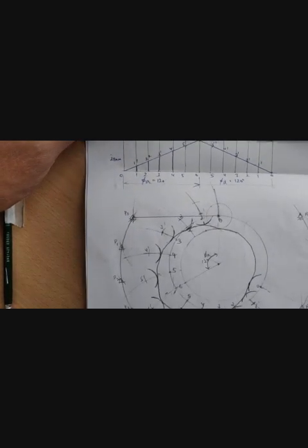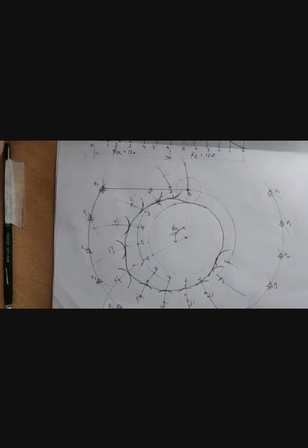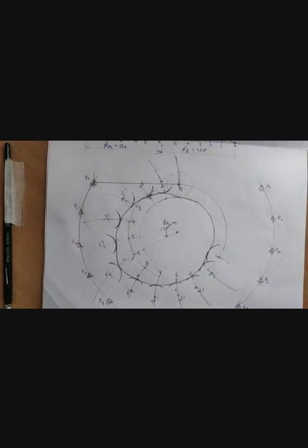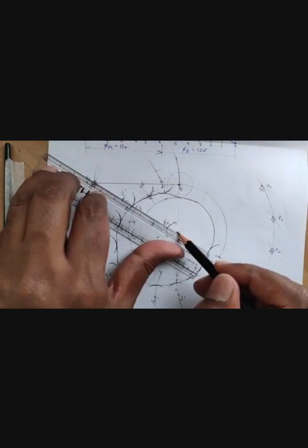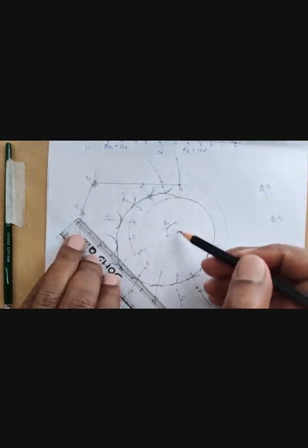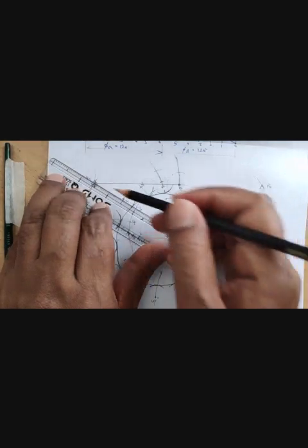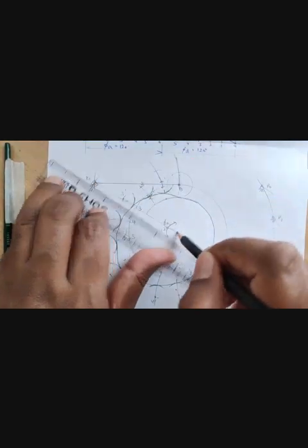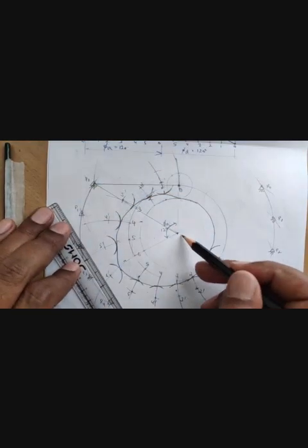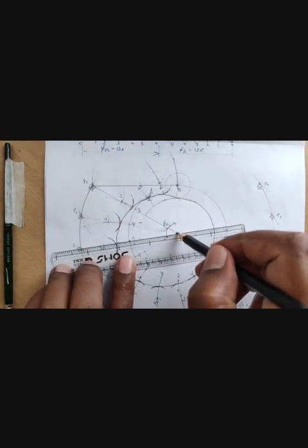And also the other mistake I made is, of course it's not a mistake, people do it that way to try to save time. They first try to take the angle, so after drawing the roller center and the pivot, the first pivot point, from here they will mark the angles first, like this, for the first 20 degree, 40 degree.